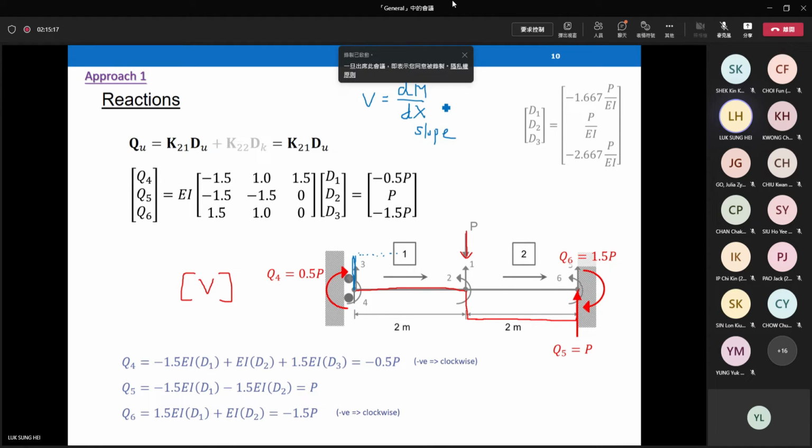From the picture, the red line shows you the shear force. Shear force is 0 along the first region, the first span. So the slope in our moment diagram is 0 in the first span. 0 slope means horizontal. And then we have a negative shear force on the second span.